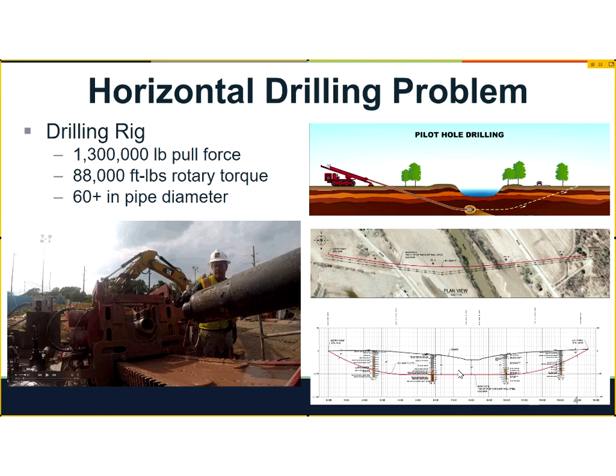The length from entry to exit can be anywhere from 800 feet to 3,000 or 6,000 to 3 or 4 miles. And for distances over 2 miles, they generally have 2 rigs. They'll have one entry point on both ends, and they will meet in the middle and bump bits in the middle, and then pull the bit through, and then finish the hole, pull the pipe through.